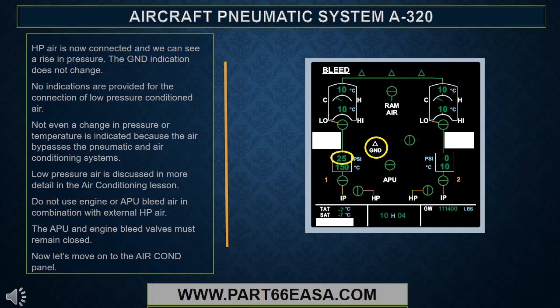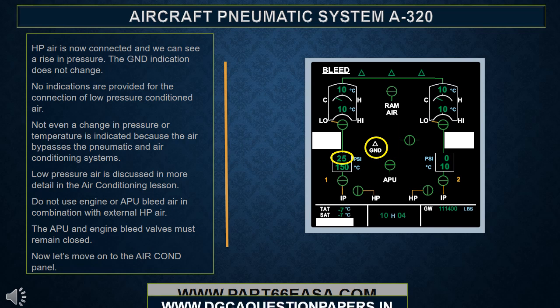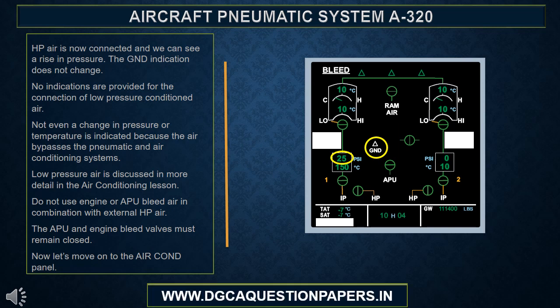Do not use engine or APU bleed air in combination with external HP air. The APU and engine bleed valves must remain closed.